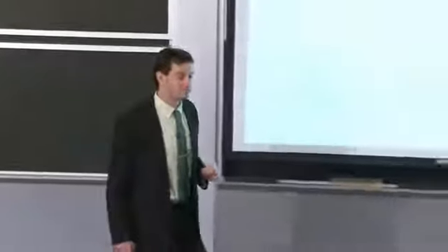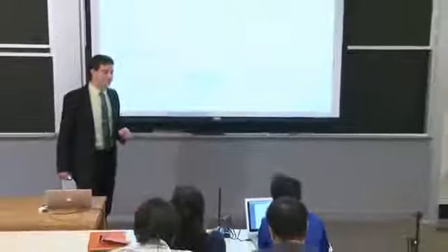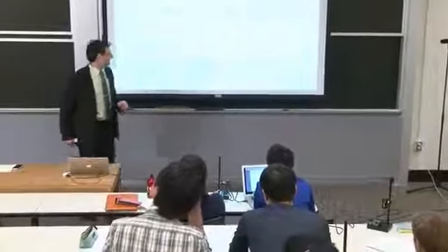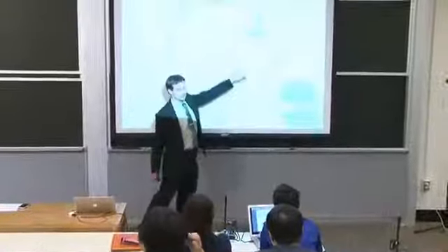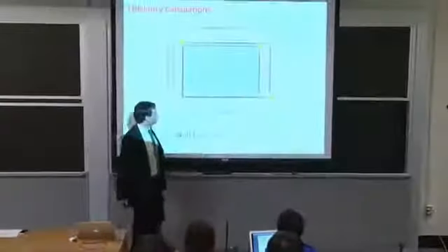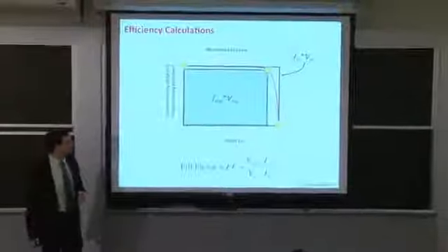Ashley. How do you, I guess, is the fill factor also an easily measurable parameter? So the fill factor you would measure essentially by doing the little analysis we just did right here. Yeah, exactly. So you'd have to do a voltage current sweep.